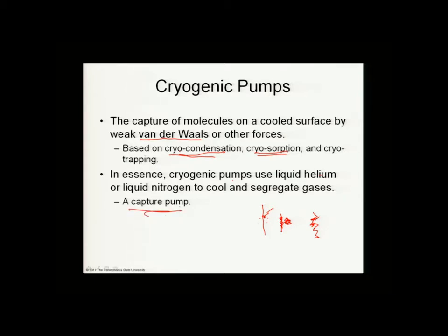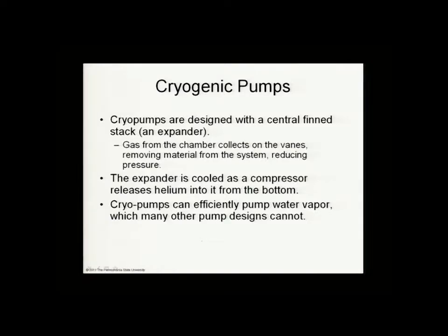It's just a pretty neat idea of taking something you see every day, well, maybe not every day, but especially in the summer, a cold glass of water causing molecules to condense on the surface, taking that idea and turning it into a very sophisticated cryopump. Cryopumps are designed with a central fin stack, and the gas from the chamber collects on the vanes of this stack, removing the gas molecules from the system, reducing the pressure. Obviously, if you take the molecules out of the system, you've reduced the pressure. There aren't as many running around anymore.